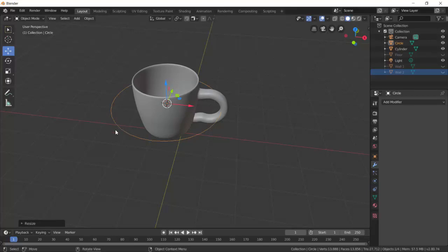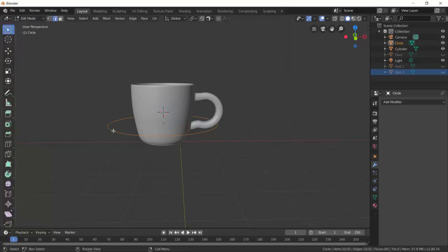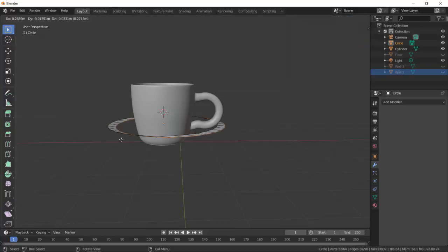And I want to make sure that I fill that face, which I can do in edit mode. Okay, so I'm going to bring that down. Edit mode. And by pressing E, extrude, you'll see it just does the edges here. I'm going to fill that face in, which we'll do in a second.